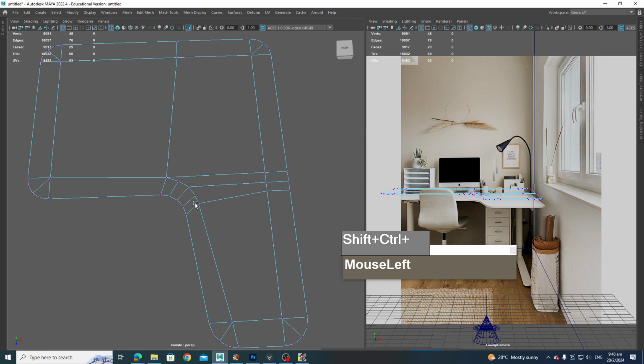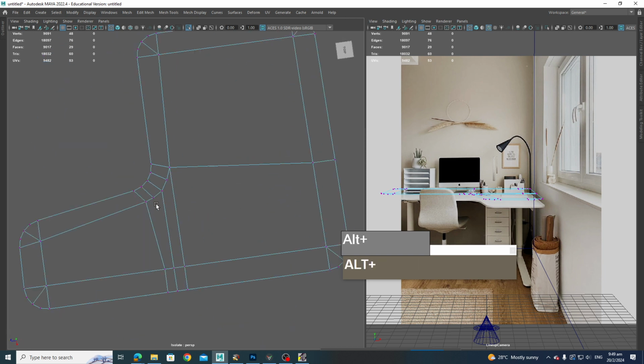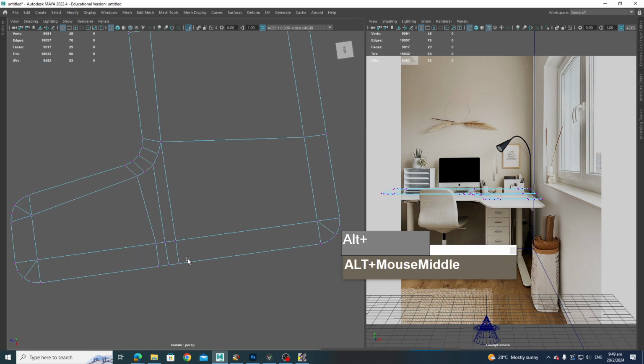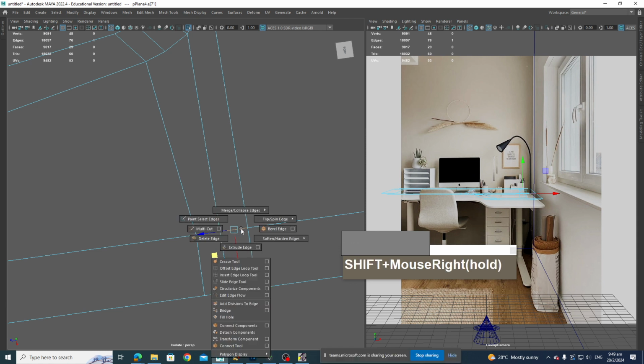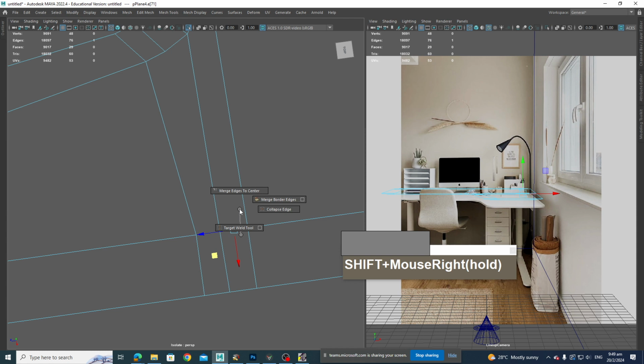Okay, so now we end up with another additional multi-sided face over here. So we're going to try to fix this by combining these two together, merging these two together, so that these will become four-sided faces. So we can select these two. Okay, I can select this edge. Let me see whether I can dissolve this. No, I think I'll merge these together. So collapse the edge.